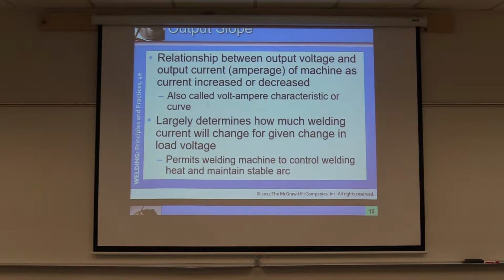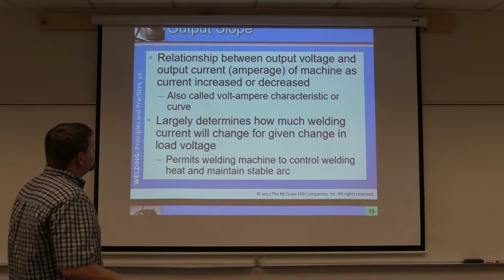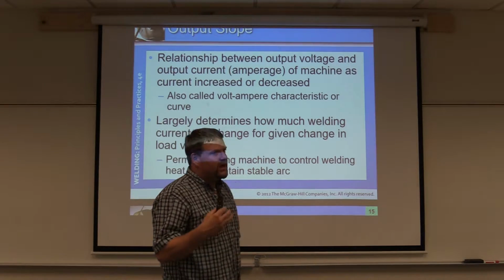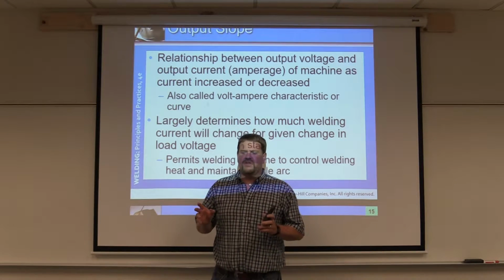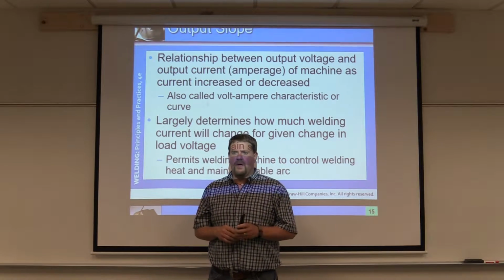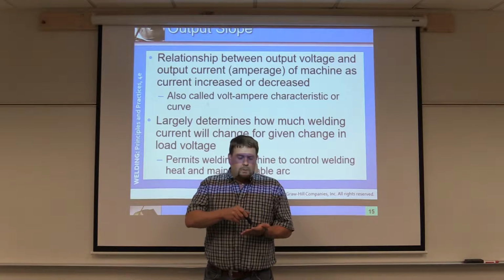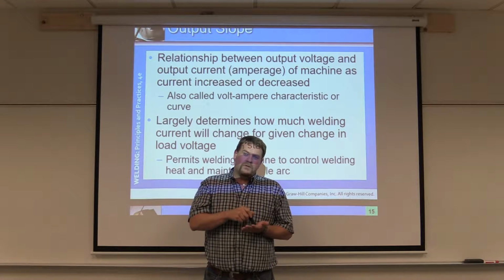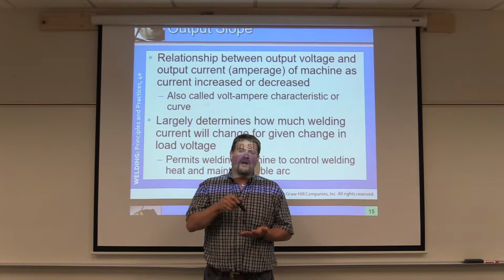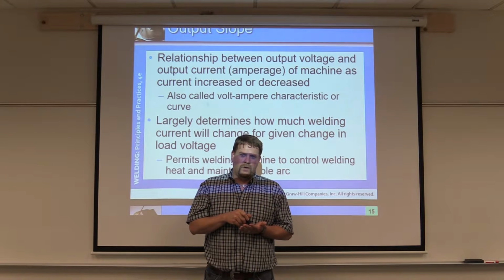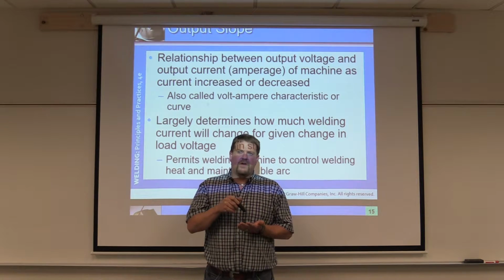But there's a whole other realm to this as well. As we get into the metallurgical part, I'm not going to go into deep detail about it, but just to get you thinking in that aspect, okay? The more voltage or the more amperage is also a direct correlation to the amount of heat input we're putting into it, okay? So we have to be very careful how much